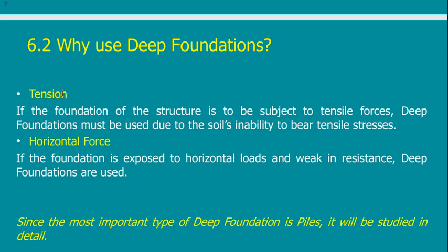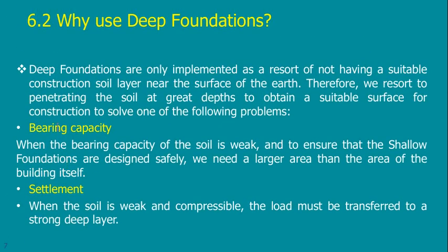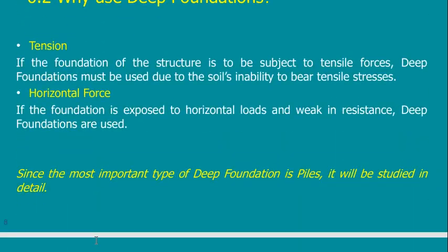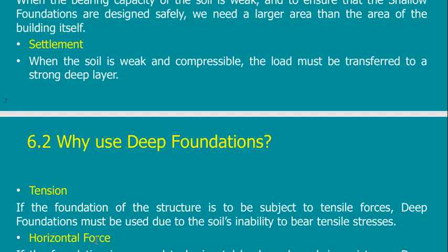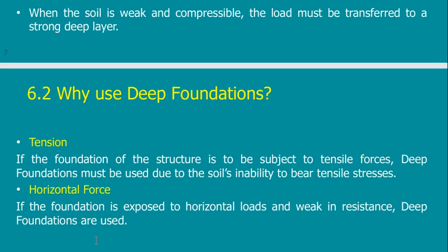Or if I have a horizontal load that is more than the friction between the shallow foundations and the soil. In these 4 cases I need to use deep foundation, and in this case I must use deep foundation regardless of the cost or the expenses of the construction.